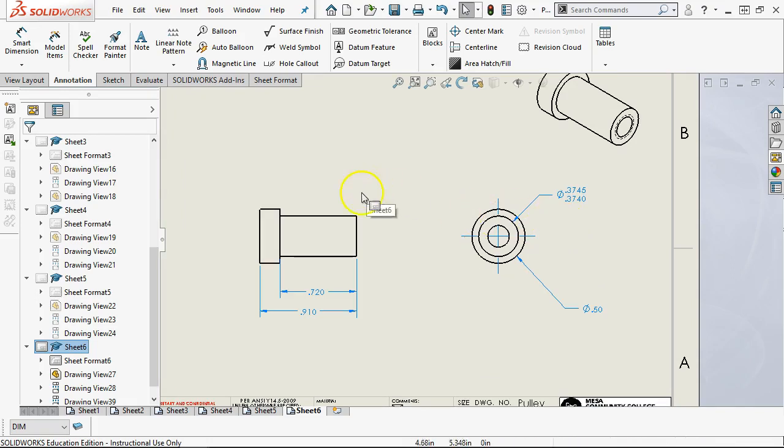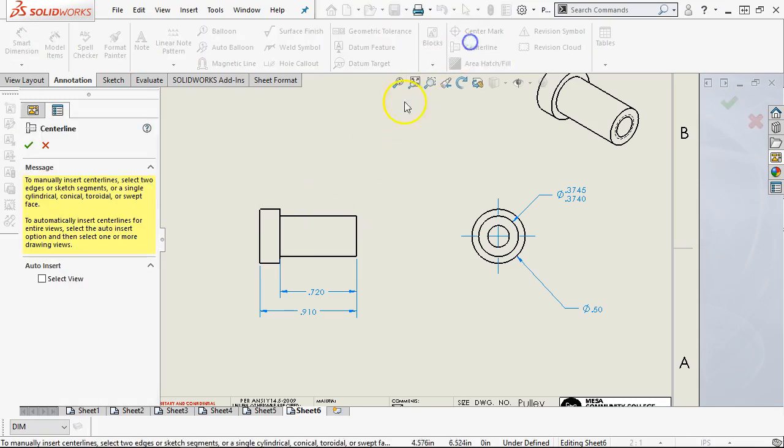All right, so our form tolerances, well, we're not really dealing with flatness here. We might be able to do across the face, but other than we said a set button head or a socketed cap screw coming into contact with this face, I don't really have much need of flatness and parallelism to the ends or perpendicular to the center line. Oh, and since I don't have a center line, let's drop one of those in. And if I pick from there to there, I should get a center line.